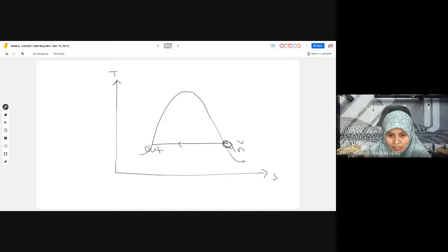After being condensed, exchanging heat with the cooling water, we expect, in an ideal process without any loss, that exiting the condensation process the refrigerant has become a saturated liquid before it continues back to the compression.